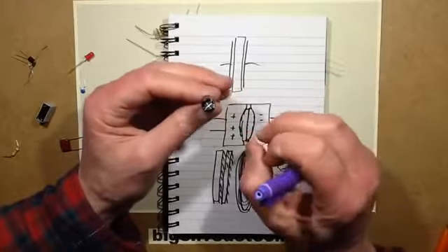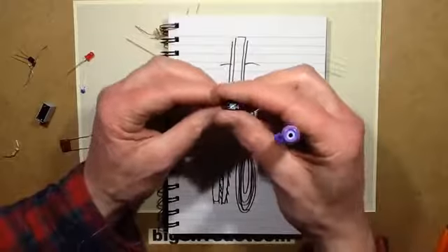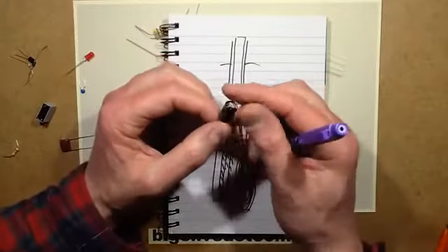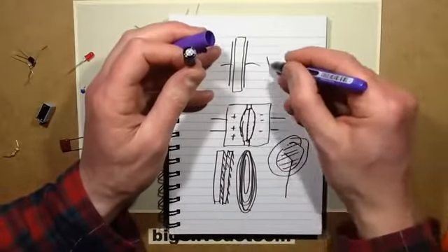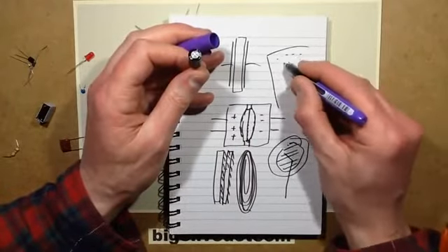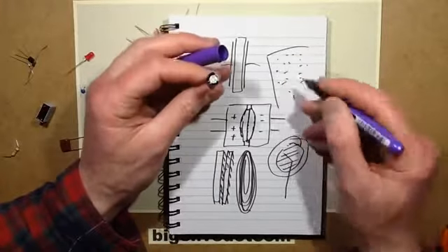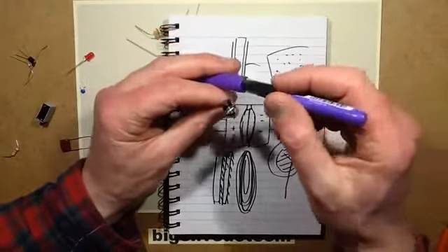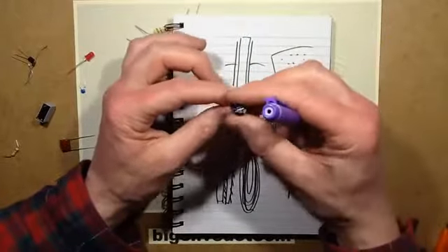That means it really is like micron thick, which means they can get a very high capacitance in a small area. But to couple onto that surface, they have to use a liquid electrolyte, because if you looked at the foil, it would look all pitted and mottled with that oxide coating. So to get a good coupling, they use a liquid that just fills in those gaps. And that's one of the downsides, well, it's many of the downsides of the electrolytic capacitor.